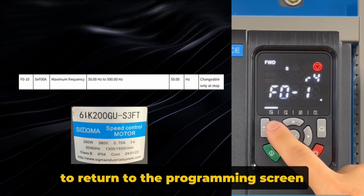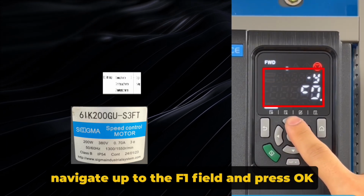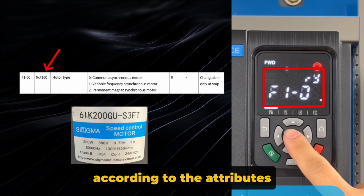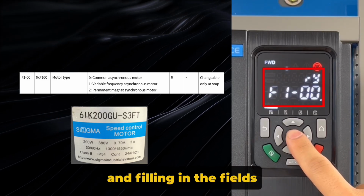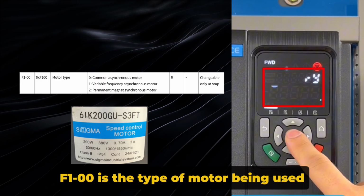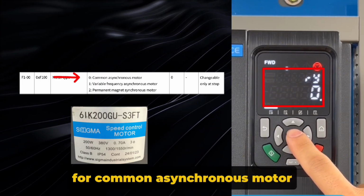Press the back button to return to the programming screen. Navigate up to the F1 field and press OK. The following fields should be filled in according to the attributes on the motor nameplate. In this example, we will be using this motor and filling in the fields as such. F1-00 is the type of motor being used. We will be keeping that at 0 for common asynchronous motor.